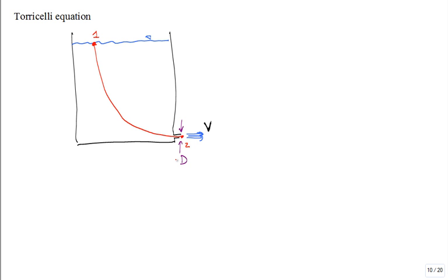All right. And I could assume things like conservation of mechanical energy along that streamline, inviscid flow, incompressible, steady flow, and so on. I know that the fluid level will be dropping, but it's like a sequence of quasi-equilibrium states. It's steady state with the flow. Okay. So if I did that, I could apply Bernoulli's along that streamline from 1 to 2. Let's think about it just up here. P1 versus P2. Which one's greater? P1 or P2?